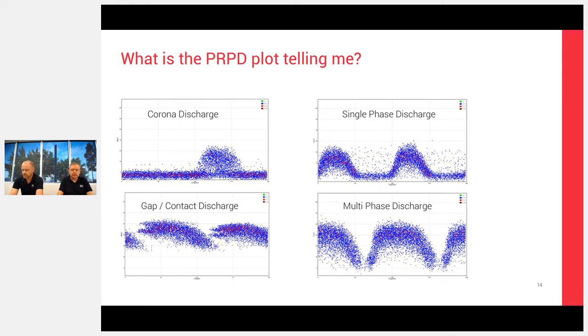We do get them happening quite a long way across the cycle. There will be these dead points in this particular instance here, you can see it, and we do see it sort of not being quite as flat towards the end of that cluster. On the TEV, it tends to stay a much flatter shape than that, but that gives us an indication. So when we get this PRPD, we can then start looking at, is it a problem? Do I need to go in? What sort of defect am I going to look for?